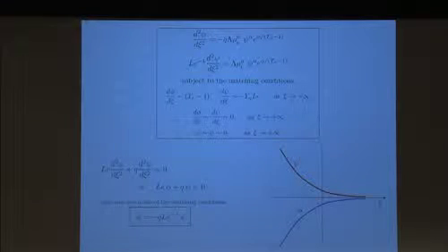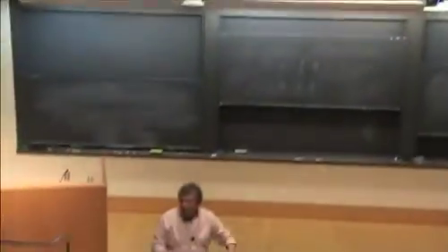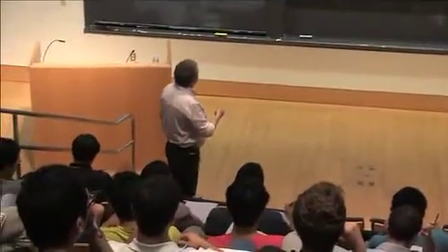They start at negative infinity with some slope. This one is positive, this one is negative, right? And they tend to 0 as you approach infinity. So you can, in principle, solve this numerically if you like, but the advantage of finding an analytical answer from here is great because it will allow me to get a clear expression for the laminar flame speed, as you shall see.